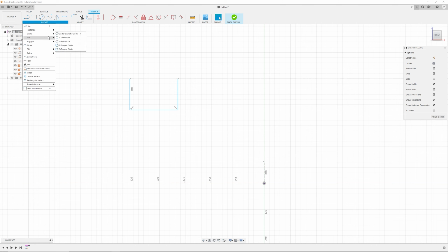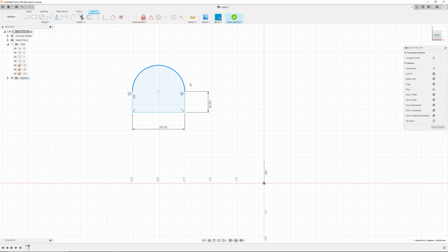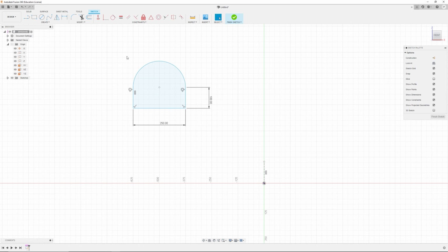I guess I would have to know how tall the center is, but you can select your starting point, your ending point, and then you can enter in whatever your radius is. In this case, I can actually just make these tangent and those tangent, and then if this had a value here, that would more or less define that, like so. Should be pretty stuck there now. Yep. So that's the 3 point.